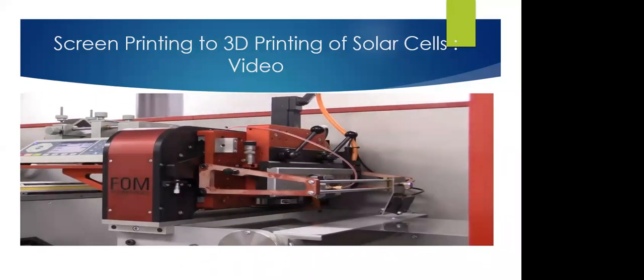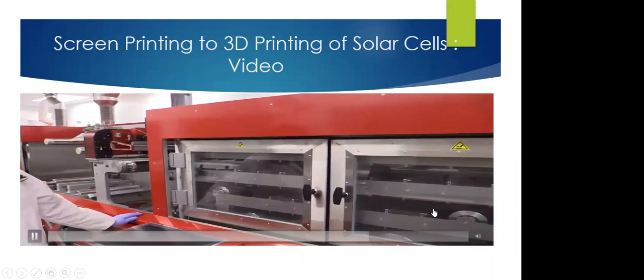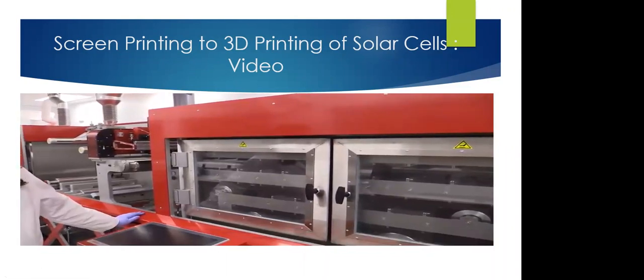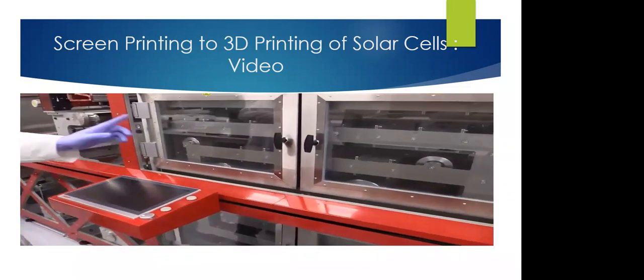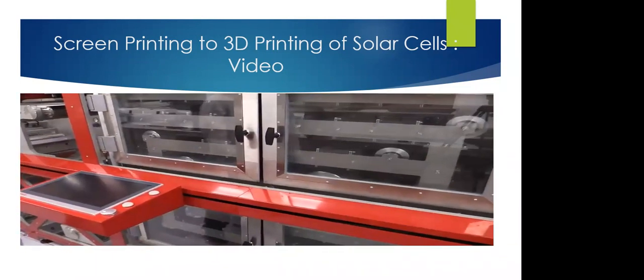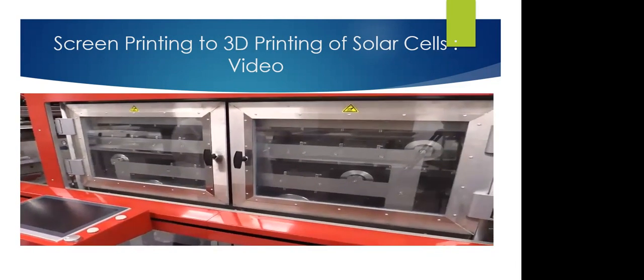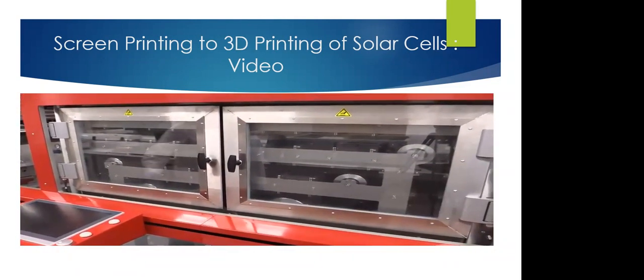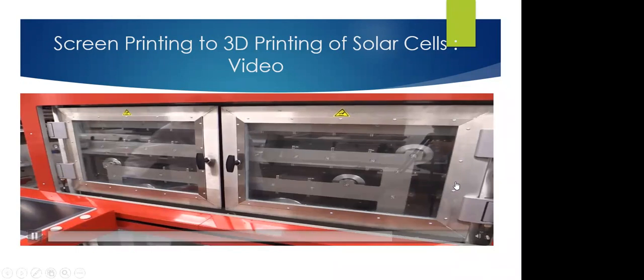So once again, after printing in a slot die coating system, we need to dry and anneal our films. So we pass through a second 12-meter oven, following the same spiral path, allowing for maximum residence time in this setup. With a lot of solar materials, your efficiency is highly dependent on annealing time. And so we're trying to ensure the maximum amount of annealing per oven length.